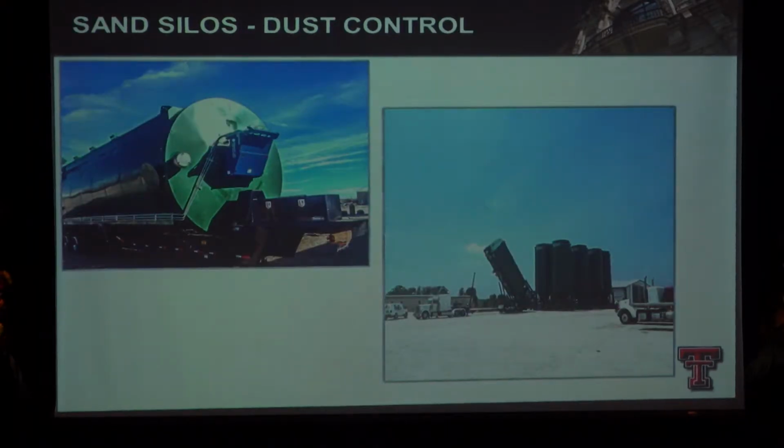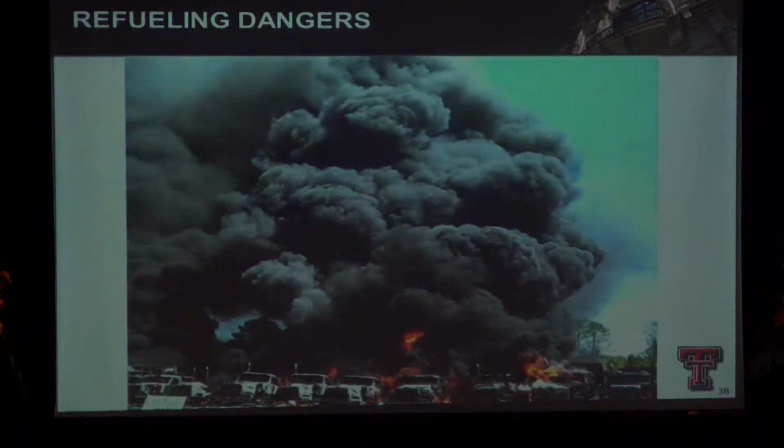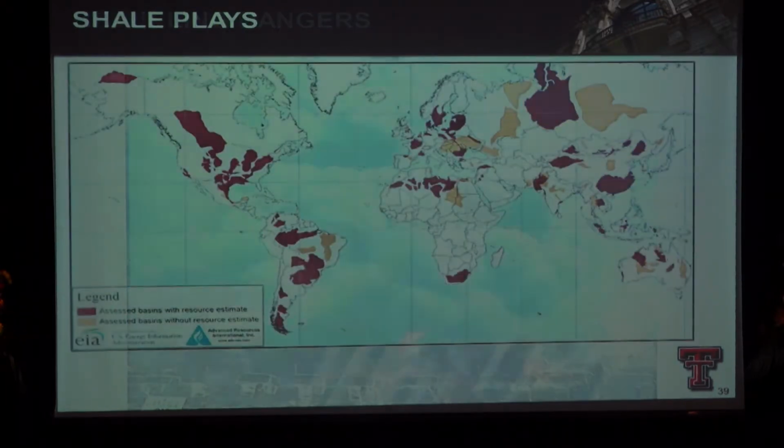Some issues or hazards you might not think of is the silica dust that is generated moving the sand to the blender to pump downhole, and we have to wear protective equipment. Refueling, as I said before, this is a 24-hour operation that may last 5 to 10 days of nonstop fracturing. So we have to refuel these trucks on a continuous basis. One of the biggest hazards we have is refueling the vehicles.